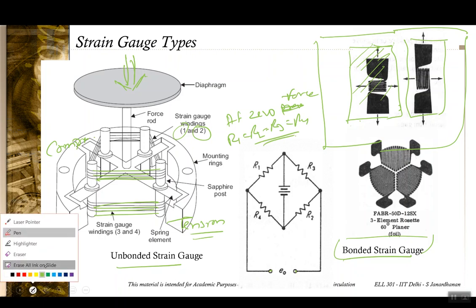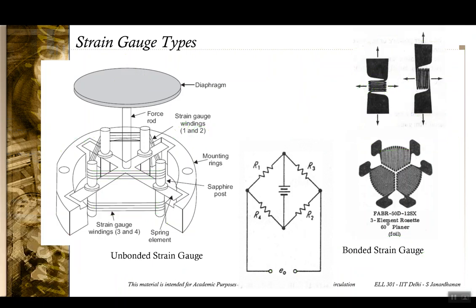Then when a force is applied, because of the compression, R1 and R2 change in one direction and R3 and R4 change in a different direction. If R1 and R2 decrease, R3 and R4 increase.